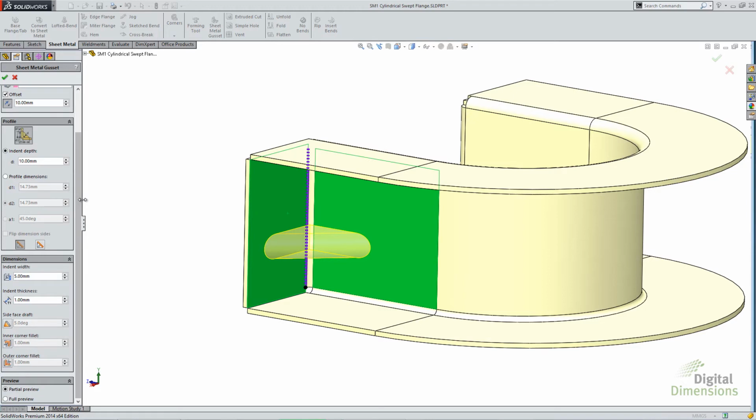The next section is where you really define the profile. If I just want a uniform size in both directions, on both faces, this direction and this direction along the face, I can just do a depth of 10, whatever that is. Obviously I have to pick something that fits within the parameters, but you can see that just adjusting it will change that size. This little picture is kind of handy. It shows you where the D1 and D2 are, and all the angle and the depth.